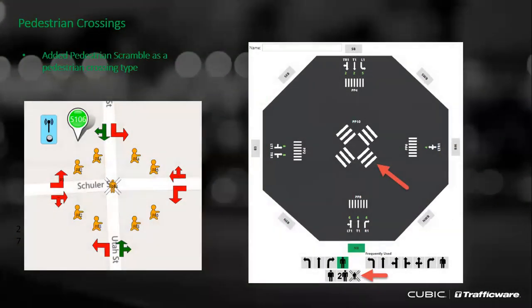Okay, yeah, this is a good example over here. You see on the right-hand side, there are predefined movements: northbound, northwest bound, westbound, southwest bound, southbound, etc. So you can create up to 8 approaches per intersection. There is no need to create a custom label. Next question is,